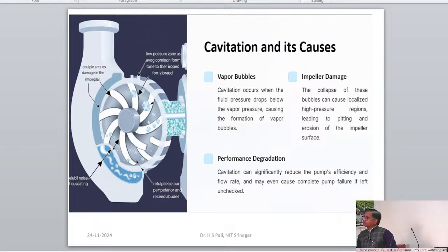To push against the water and hold it as high as it possibly can within the pipe. At this point, it's just spinning the same bit of water, which isn't good for the pump, so you don't want to run a pump like this in the real world. By recording the values during the elevation, we basically get a pump curve, although I will note that pump manufacturers don't test pumps this way because it's just not practical. So what is the purpose of showing this curve?